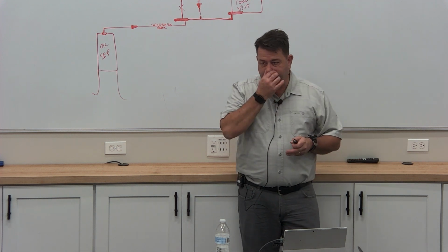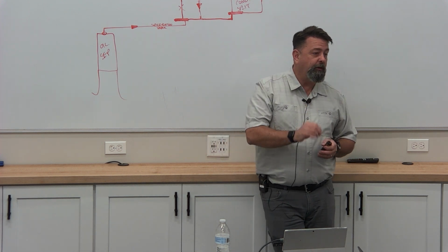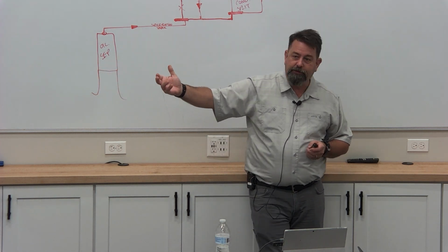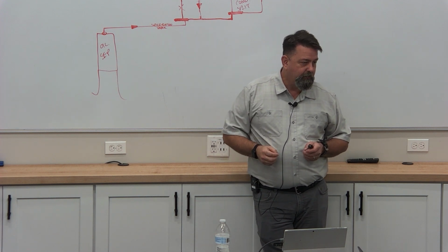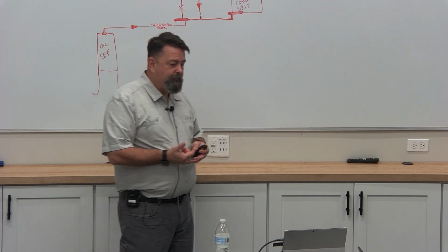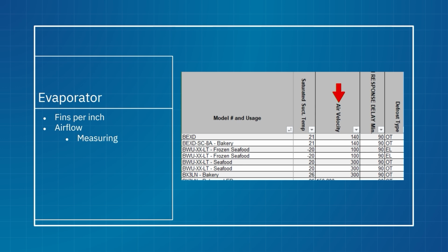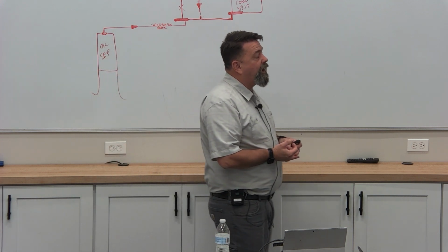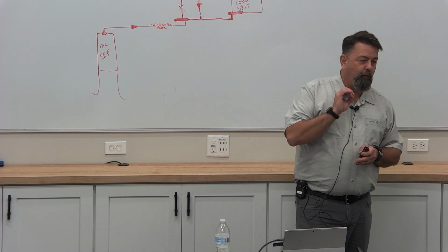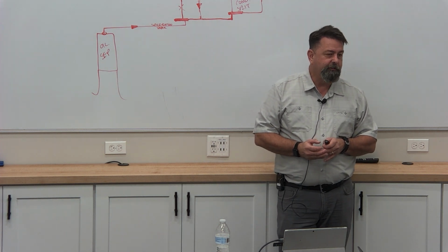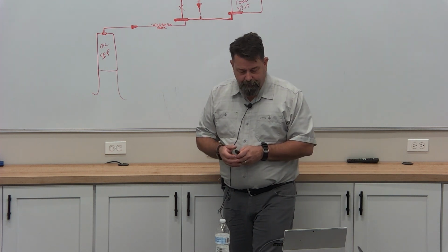All right? CFM, right? I'm telling you this because when you look on the manufacturer's page, you may find the Canadian version and it's meters, right? It's gonna be a totally different number. So we're talking about cubic feet per minute. That's how we measure airflow, all right? CFMs. This particular case is gonna be blowing 140. What does that mean? I can take this reading a lot of different places, a lot of different ways. I'm gonna get a lot of different results. So the reason why I'm not gonna walk up to this case and read 140, there's a couple reasons, okay? But I'm not.